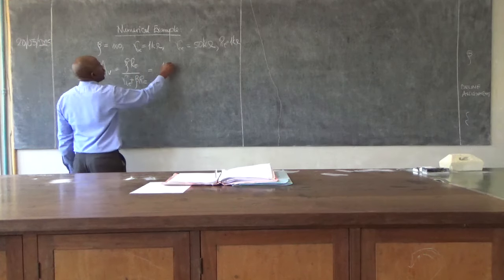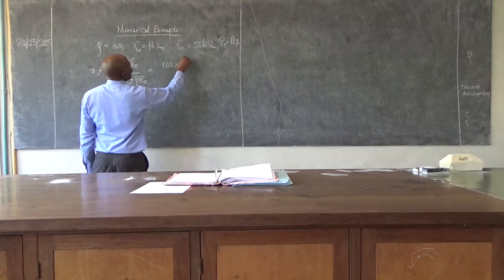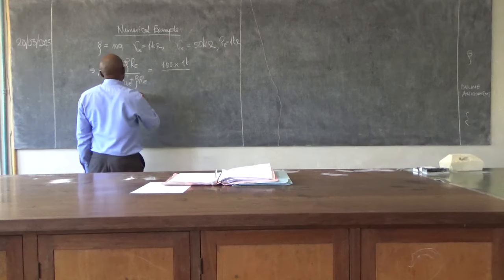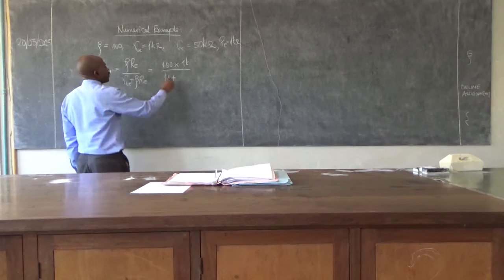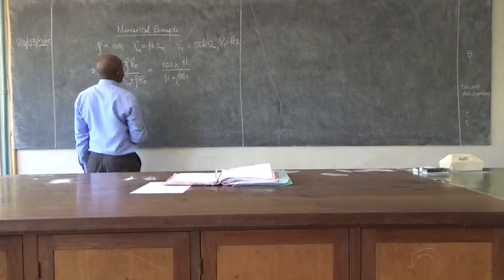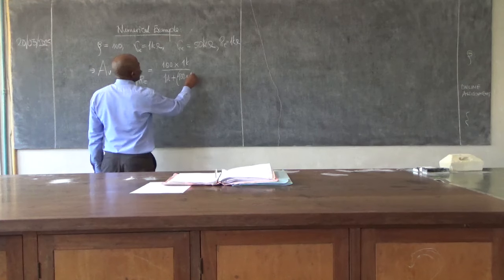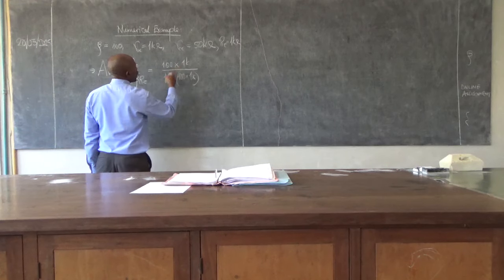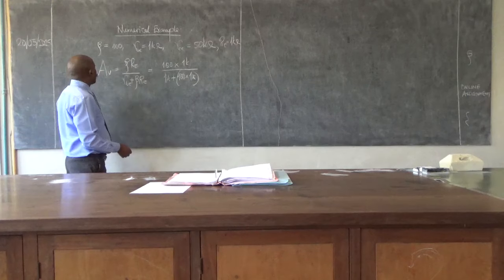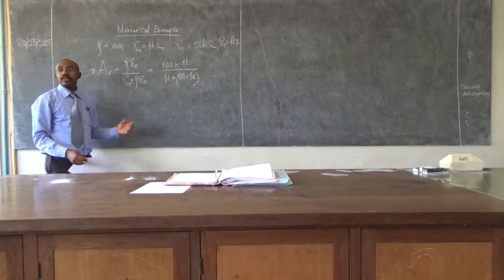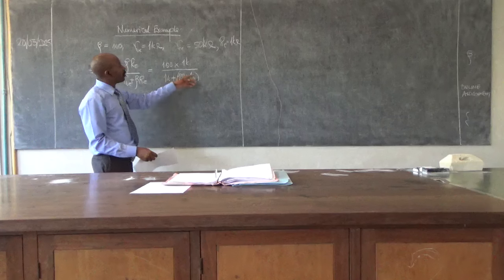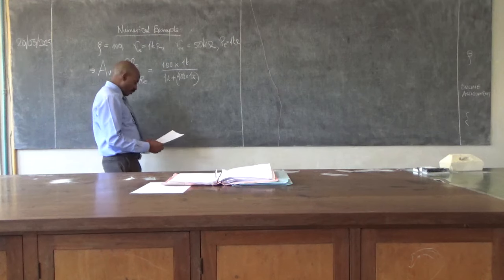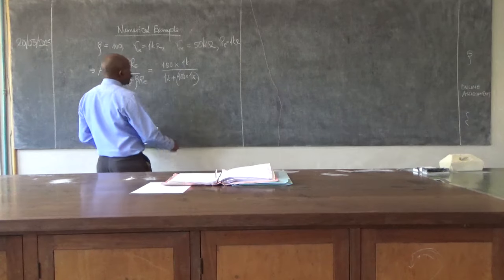Beta is 100 times RE 1 kilo over RBE 1 kilo plus beta, which is 100 times RE, which is 1 kilo. The kilo ohms go away, and we are looking for amplification. Amplification is the ratio of voltages, so it is dimensionless, it has no units. That's why I'm not bothering to put the ohms.